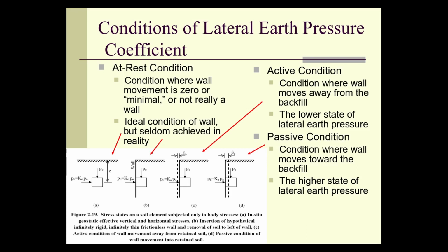The at-rest condition is important not as much for lateral earth pressures as it is for the estimation when you're talking about if I apply a vertical stress in the soil mass, what will the horizontal stress look like without any retaining wall around? That's where the at-rest condition is most of the time experienced.